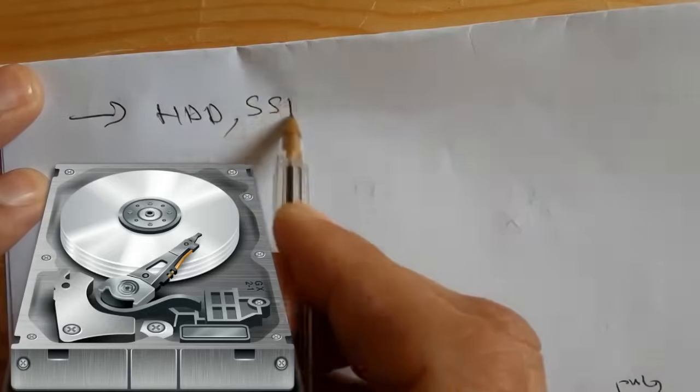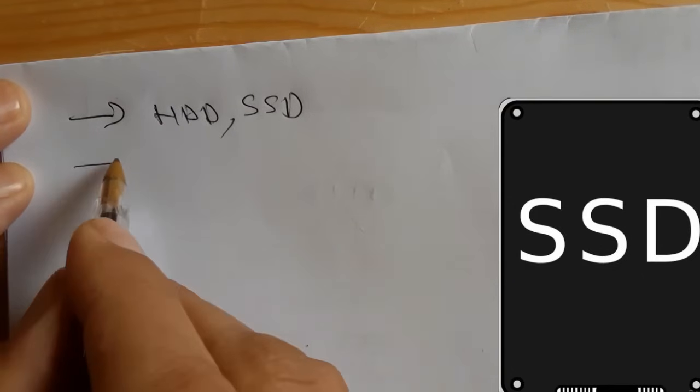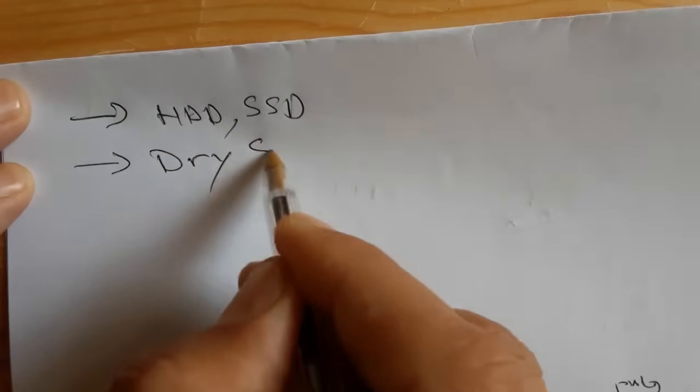So the next fault that you can get in laptop motherboards is the HDD or SSD failure. The HDD means the hard disk drive, and the SSD means the solid state drive. This is an enhanced drive. So sometimes you can find a problem, no data in the laptop, and you should check the hard disk drive connector. Maybe the hard disk drive is not connected properly.